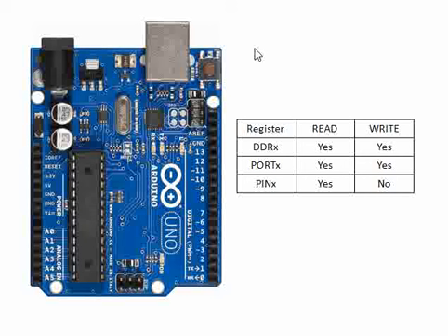If you write the program without knowing that, you might read or write a register which is not allowed to be read or written, and then it might give an error at a later point of time, which is not a good thing. You waste a lot of time programming. So before doing that, you need to know which registers are readable and which registers can be written.